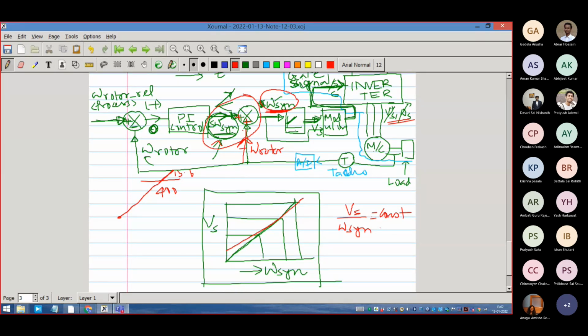For example, our supply system is near to 50 Hz, but never exactly at 50 Hz. But the variation is within 2.5%. So in order to make a guess, do I start guessing from 0? I will not start guessing from 0. I already know it is close to 50. So I will start putting 50 first, and then let the controller adjust the difference.